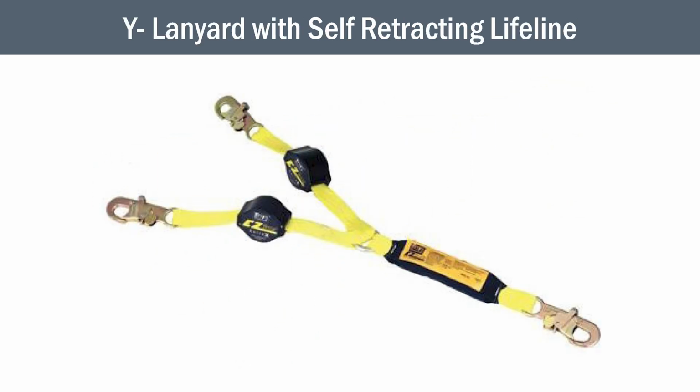Then you have self-retracting lanyards. I haven't seen the cost lately. At one time, they were about $300 a set. With inflation, it could be higher than that now. Some people like these. And usually what you see this used for is to shorten your free fall distance. Okay. And if you're moving, like let's say you're getting off of a scaffold and you're crawling onto a building, then you want to connect to that building before you disconnect from your scaffold.